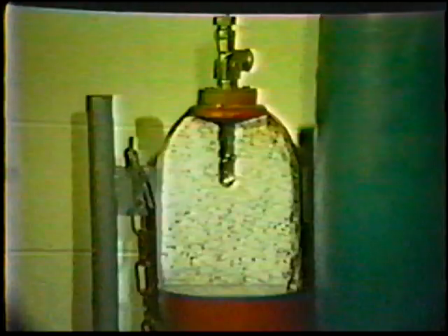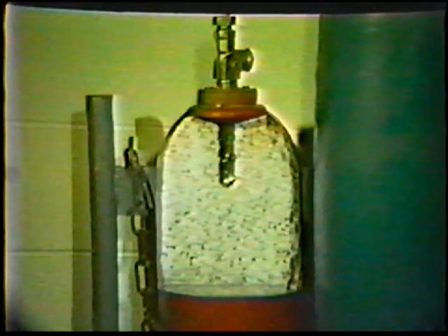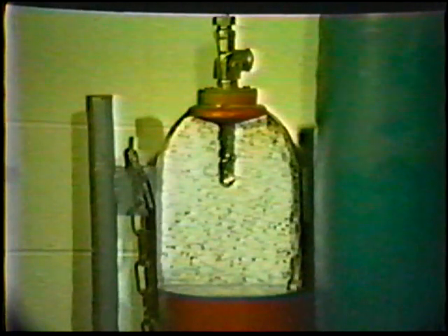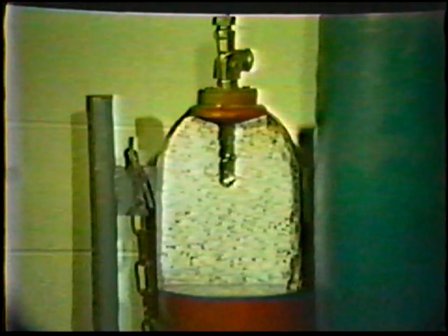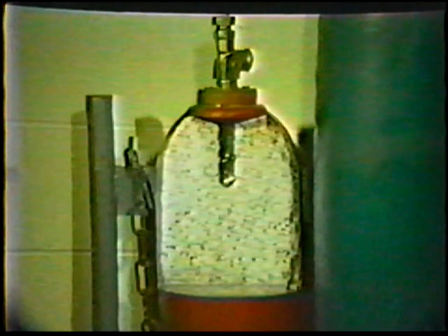Acetylene is often supplied in cylinders at a much lower pressure for safety reasons. It may also be supplied from a generator, which uses calcium carbide and water to form the gas. Acetylene by itself cannot be safely used at pressures above 15 pounds per square inch. When it is stored in tanks at 250 psi, it is dissolved in acetone, which is absorbed in a porous material made from pumice, balsa wood, or other material. The acetylene cylinder must also be treated carefully and inspected at intervals.